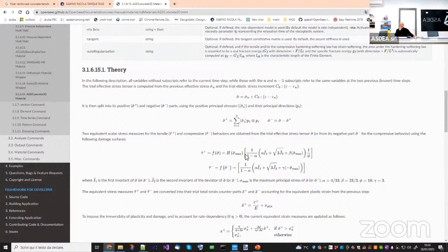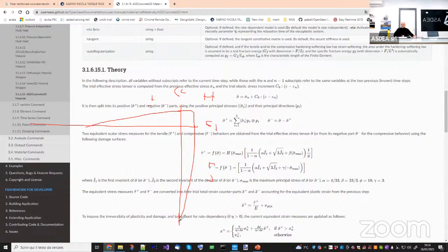And this term here is used to deactivate the surface only when all the eigenvalues are negative. Just to explain, in plane stress condition, sigma 1, sigma 2, the tensile surface will be something like this. It will be active on the sides where you have positive and negative eigenvalues. Here it will not be active, so the surface expands infinitely in this direction. This makes sense because you don't want the negative stresses to affect the tensile surface.